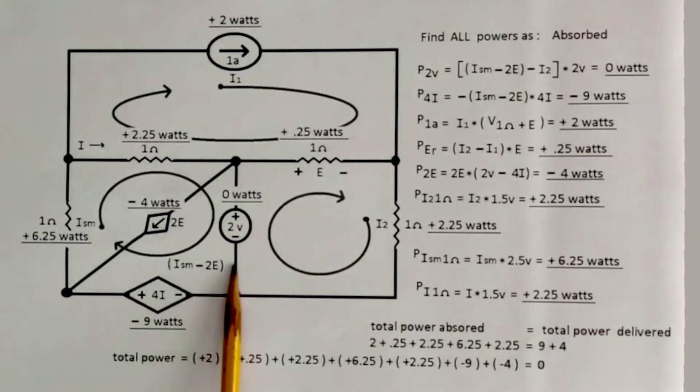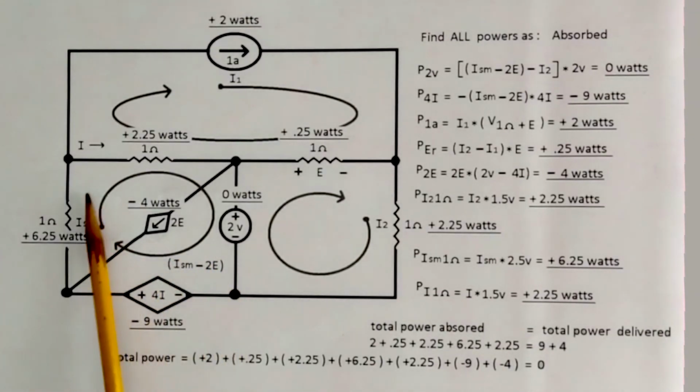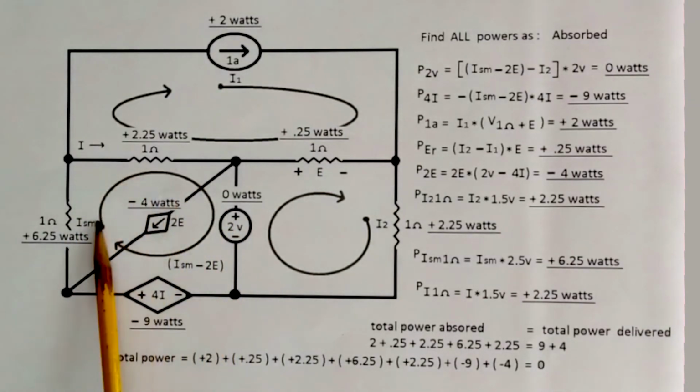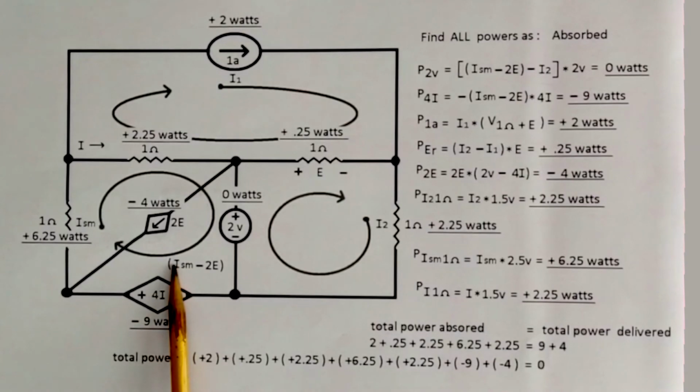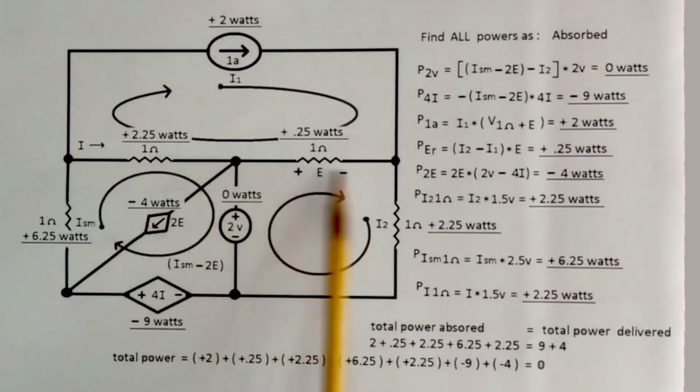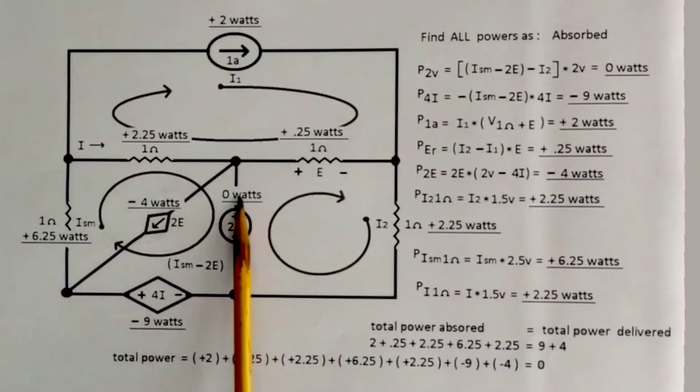We'd have a supplemental equation here we'd have to substitute back in. Doing this technique, we eliminated the need of drawing 2 additional mesh currents, and the supplemental equation is kind of already incorporated here.